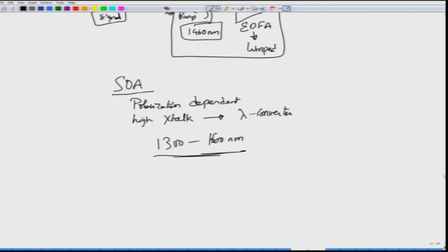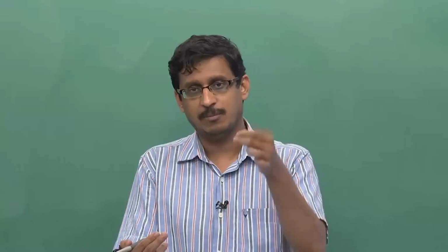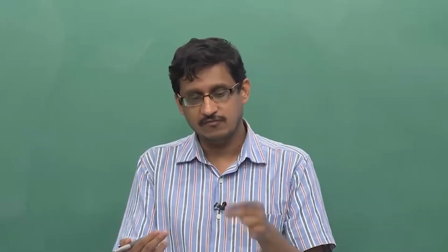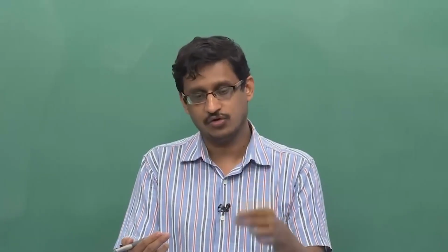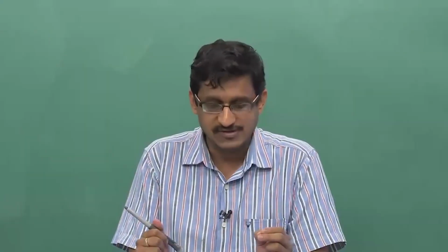The construction of an SOA is very similar to the double heterostructure laser diode that we talked about. The pump is from the current, and the pump is in the transverse direction. Everything that we talked about for lasers holds for semiconductor optical amplifiers as well.